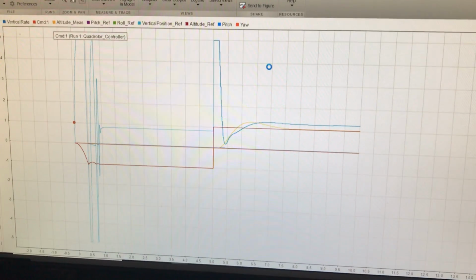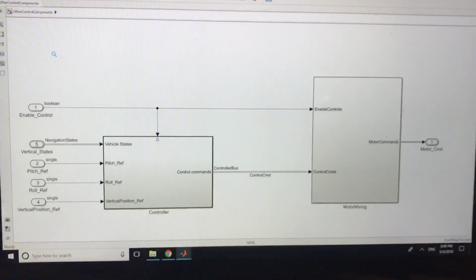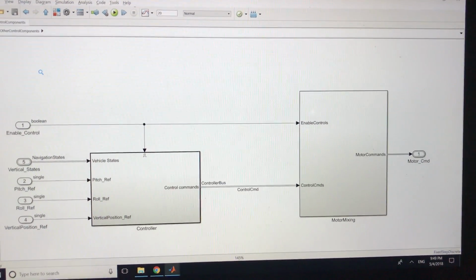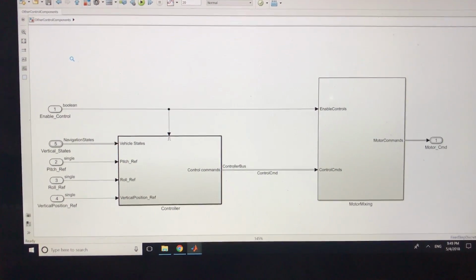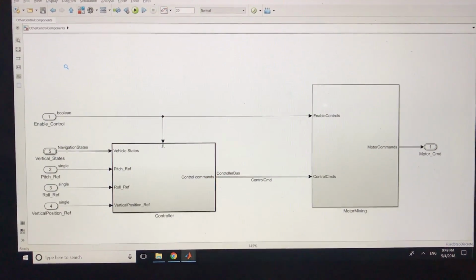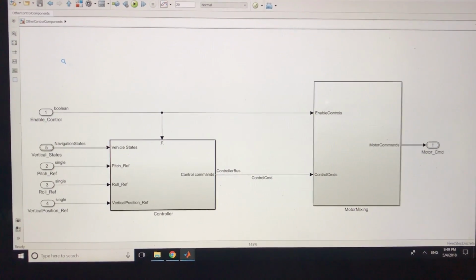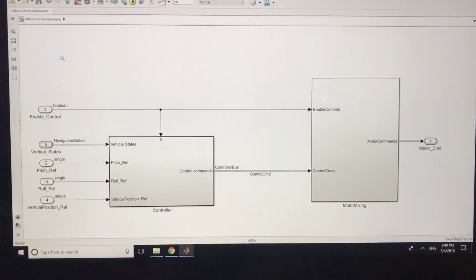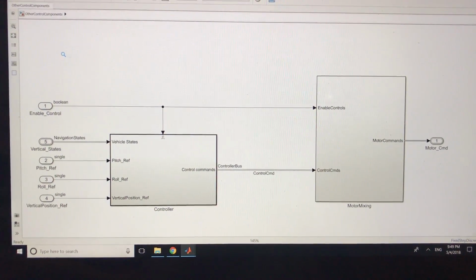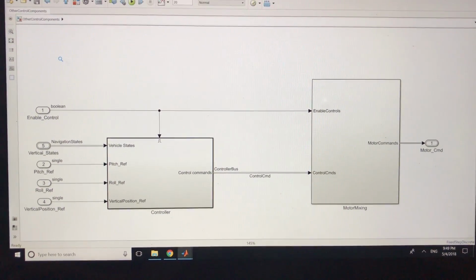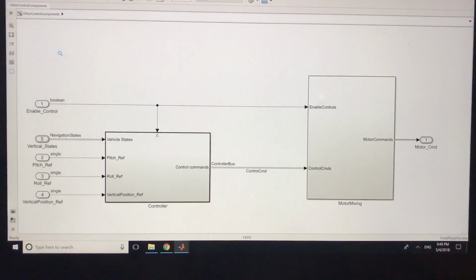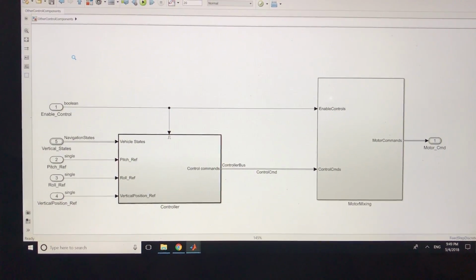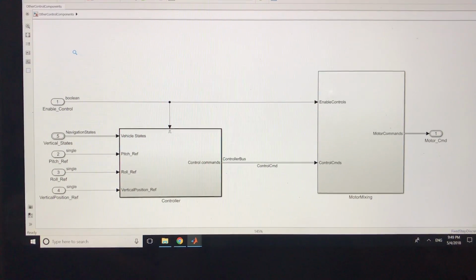And then for errors in the system, what we determined is, with a PID control system, you're trying to measure your position to get to a certain reference point, and say you had a disturbance. There are a lot of disturbances for quadcopters, such as noise in the system, and the biggest one would be physical disturbances such as wind and obstacles. It's really hard, especially for wind, for a PID controller to take that into consideration and adapt and modify itself to solve that problem.